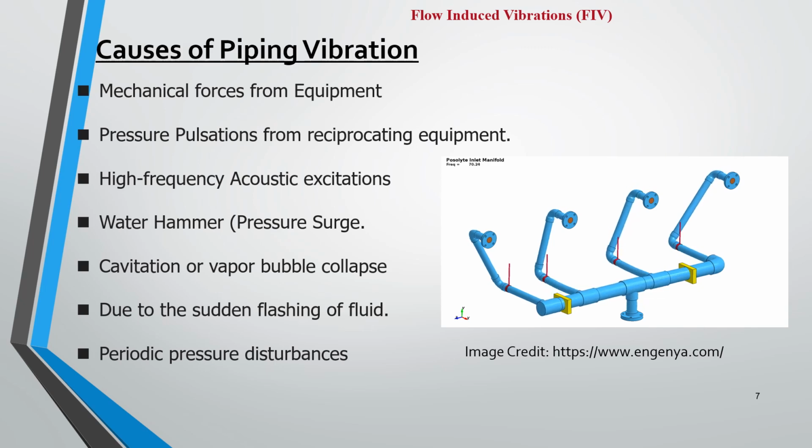So if there is a dead end in the system or an instrument item, periodic pressure disturbance also may happen. So all these reasons can cause piping vibrations.